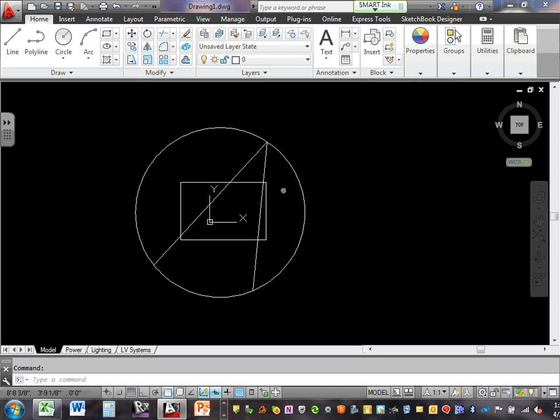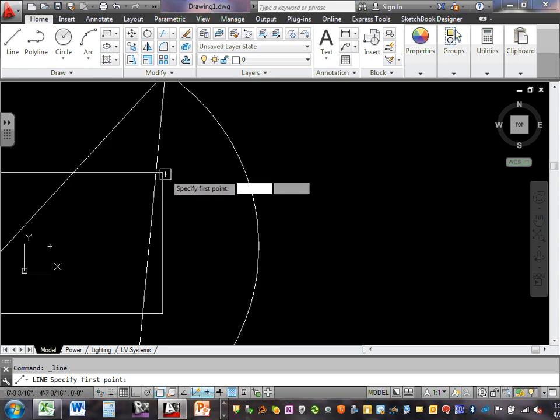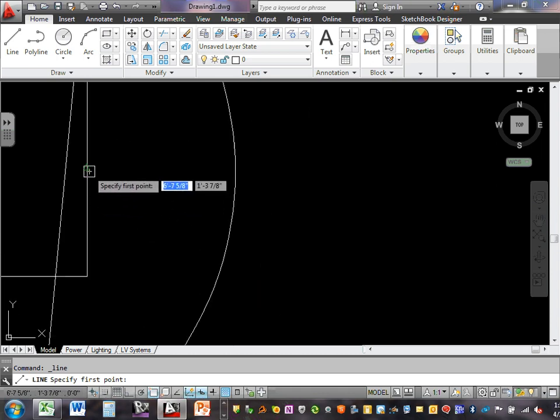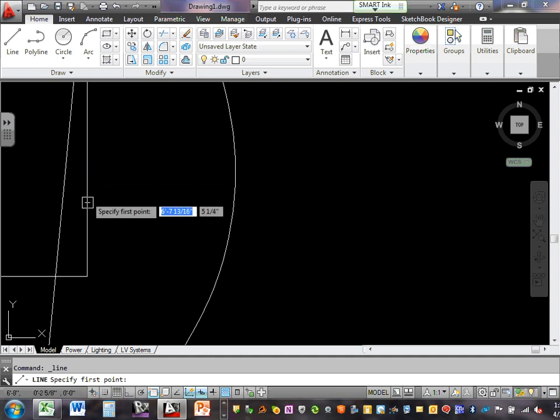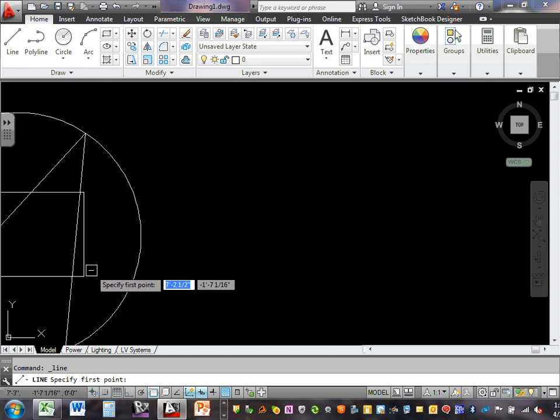We okayed it. Now, if I'm going to draw a line, guys, click on the line. When you hover over the line, do you see these little green things popping up? So this will mean you snap it to here. Do you snap it to the end? Look at that. And now again, snap to the end. Can you guys see how nice the snap is? I come over here. It tells you, oh, here you can snap it. Can you guys see you snap to the center of this line? Or to the line, or to the corner. It gives you different symbols to snap to.